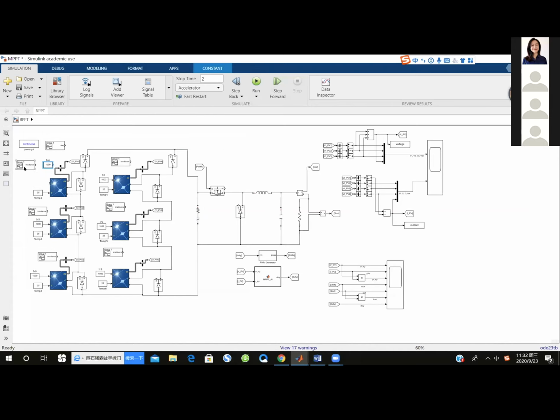While you are trying the task 2, I'm answering other students' questions, and when you finish everything, you share your screen and we will solve your problem later, okay? Okay, thank you. I got the duty cycle for around 0.4. This depends on the load you are choosing. If your load is the same as mine, I chose a 10 ohm load, then 0.4 is good. Whether it's right or wrong only depends on the power you got. If the power is the maximum power, then that's good.